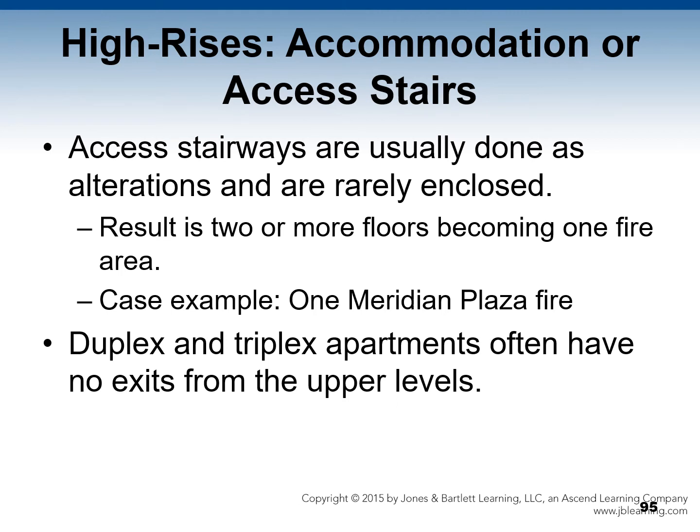With high-rises, let's talk about accommodation or access stairs. Many tenants have an accommodation or access stairway installed. This is usually done as an alteration and is rarely enclosed. The result is 2 or more floors becoming one fire area. One case example, again, is the 1991 One Meridian Plaza fire in Philadelphia. In this case, fire was seen falling down through such an accommodation stairway from the 22nd to the 21st floor.